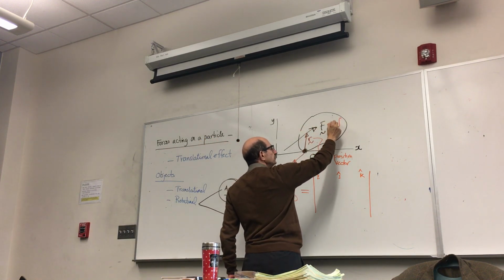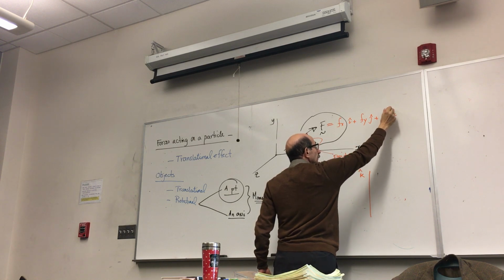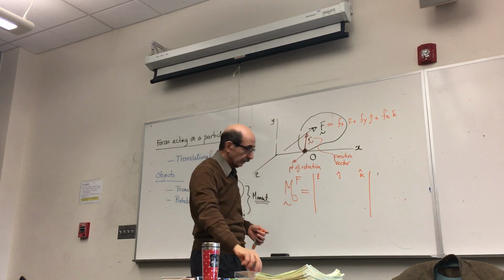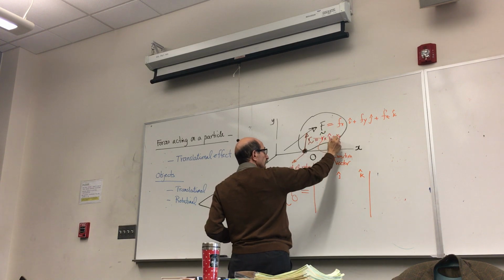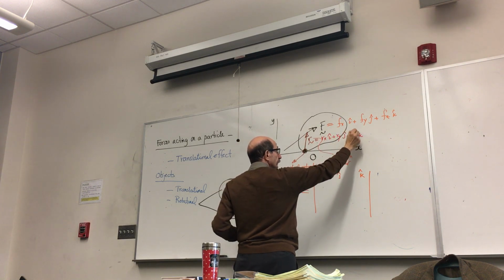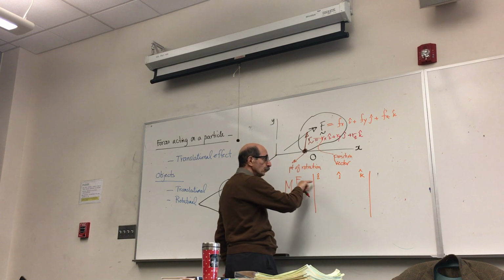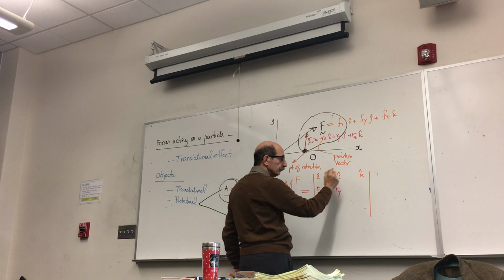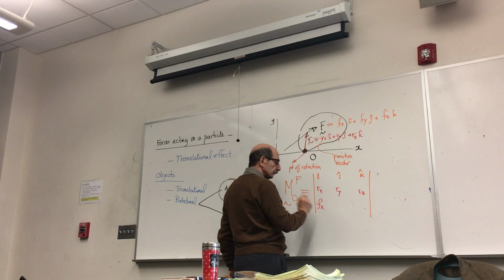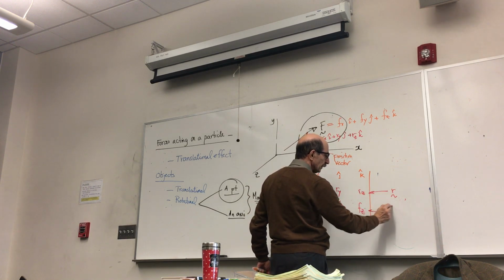Obviously, a force can be written in vector form, right? We know how by now. Any force can be written as a vector like that, and this position vector can also be written, as long as we have all the information about the coordinates of these two points. So the moment can be fully described by expanding a determinant whose first row consists of I, J, K. The second row are the components of the position vector, and the third row are the components of the applied force. So this is R, this is F.